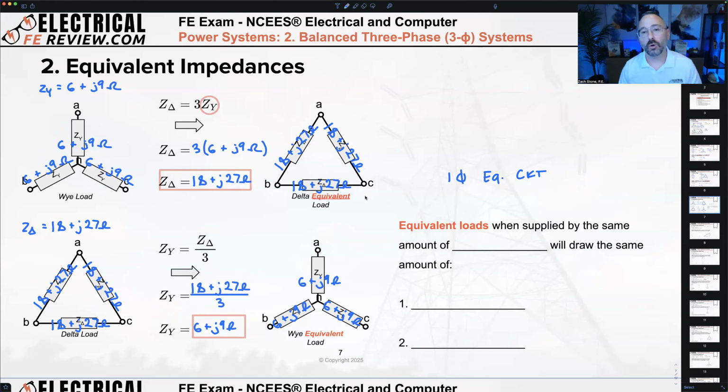So it's not like, maybe I've got a motor or transformer, and I'm opening it up and rearranging the impedances per phase, right? The word equivalent just means we're modeling: if I had a Y impedance instead of the delta impedance, how big would that Y impedance be? Or if this Y impedance was a delta impedance instead, how big would that delta impedance need to be so that essentially there's no change seen by the system? So I can use it to simplify analysis.